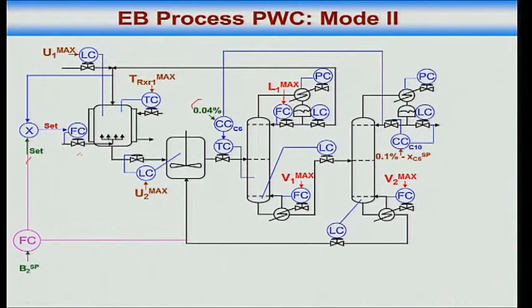We do this. This, or you can even control a temperature. If ethyl benzene drops down, this flow will increase. The bottom flow, this flow will increase. If ethyl benzene is dropping down, composition, I don't want to measure compositions, because composition is the only product purity you will get, nothing else you will get. You are still supposed to operate it without any composition. Temperature, pressures, flows, that's all that's available. Composition very rarely. The only place where people are willing to measure compositions is the product, because that's what they are supposed to sell. They have to guarantee to the customer, so okay, there they'll make some measurements, but the rest is not available.